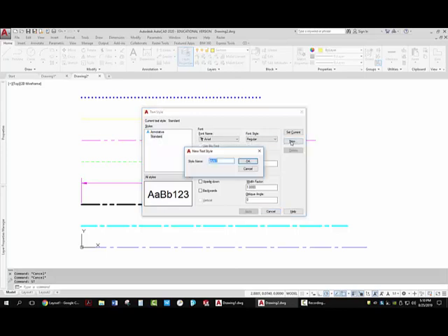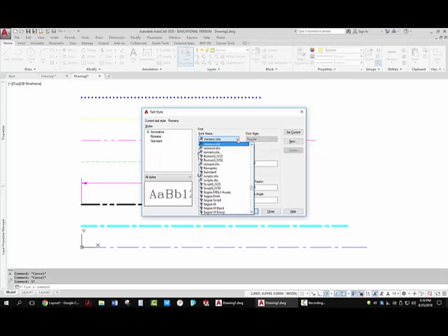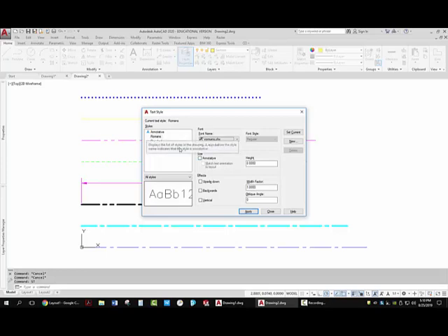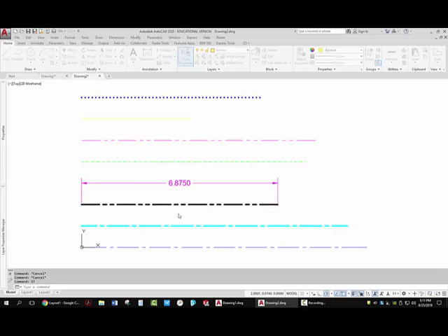So I'm going to create a new style, call it Roman S. Roman S is a style name that's going to reflect when we change the font used to define that style. Roman S meets all drafting standards. So I'm going to call that Roman S, and most of the time our text is going to be annotative, so I'm going to make that annotative. I'm going to set it current, and now I'm going to come out and I'm going to place some text.